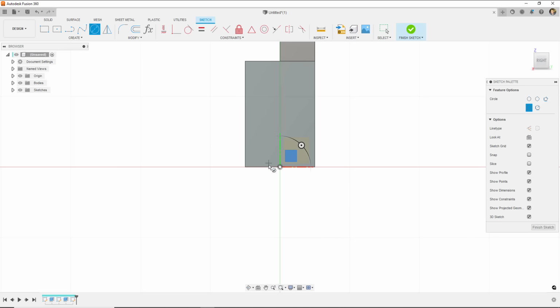Okay, so try that. Just go up from the midpoint there until you get a blue line from the midpoint here, or vice versa. Try it from the midpoint there until it snaps onto a center line. But you'll see your cursor kind of wants to snap into that middle point. When you're there, left click once, you'll now have the circle. And it's the same as when we drew our square, except with the circle you've only got one dimension, diameter.